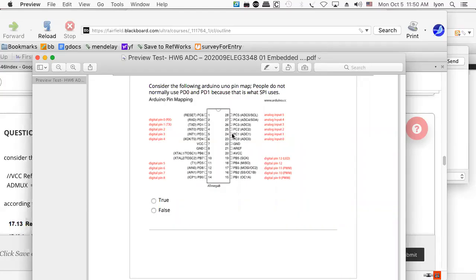And that's going to impact my sample rate, my conversions, perhaps even my overall dynamic range. I may not be able to use all 10 bits worth of A to D conversion if I go through all of these inputs. And here's the other thing. It looks like there's a 2-wire interface being reused for inputs 4 and 5. So if I want to use 2-wire input, it will conflict with ADC inputs 4 and 5. That's no good, so I probably don't want to use those first. So there's a couple of problems here. You can see this right here with the chip.